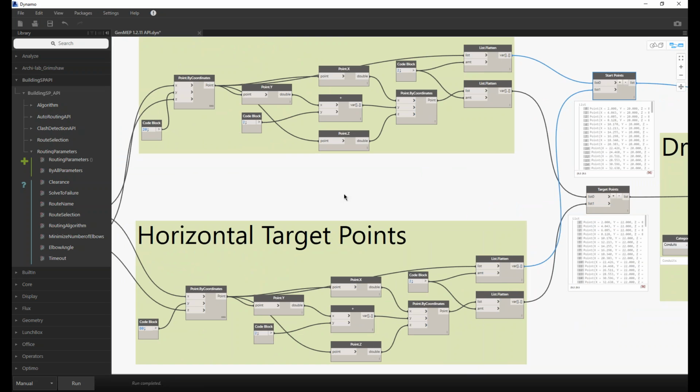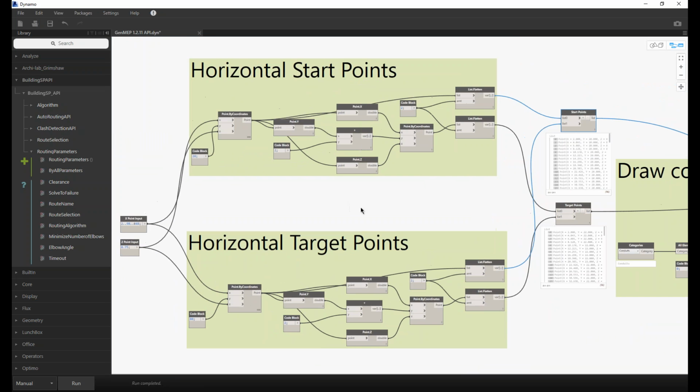One other piece of functionality that we have, which we think is important for the generative design portion of all this, is an interrogation tool for MEP systems. So if you define, for example, a duct run, it'll return values for that duct run that you can look at, for example the head loss, the amount of linear feet, or the number of bends.